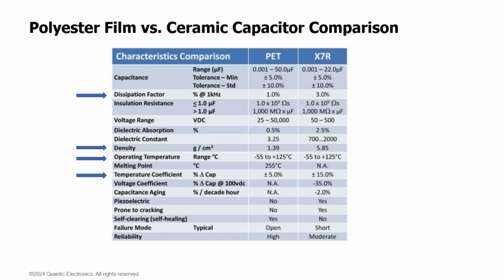Also with ceramics, extremely high breakdown temperatures of the ceramic capacitors make them great for high temperature applications. And film is sort of moving in this direction. We've made a lot of innovations. So some films can go up to 200 degrees C now. But again, ceramics, very hard to beat temperature-wise.